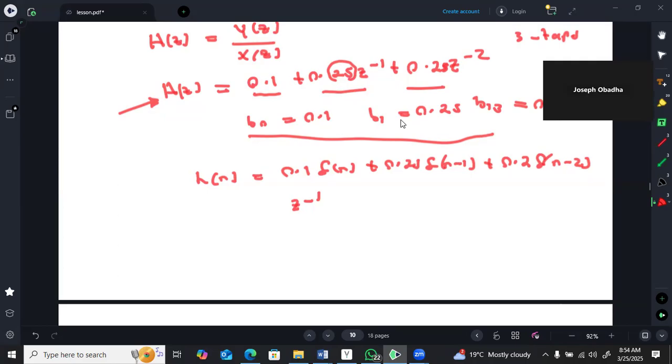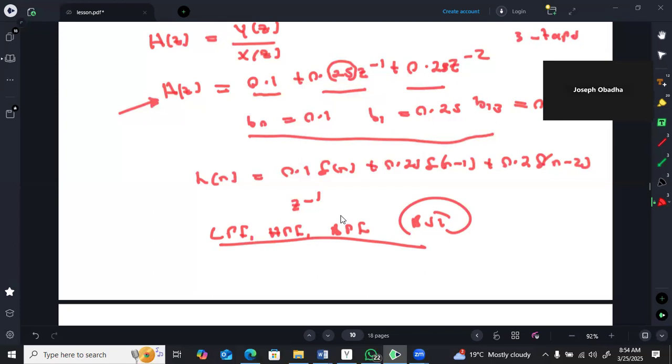Okay, so the design objective is to obtain the FIR filter coefficients b i such that the magnitude of the frequency response, such as the low pass filter, the high pass filter, band pass filter, or band stop filter, are realized depending on what we want to do with the filter. And filters find wide application in all electronic systems, transmission systems, components we use for different purposes everywhere.